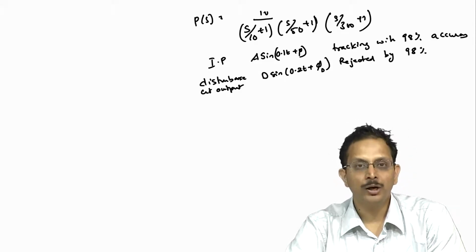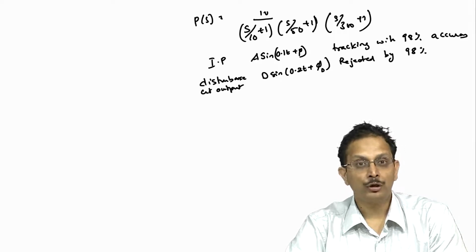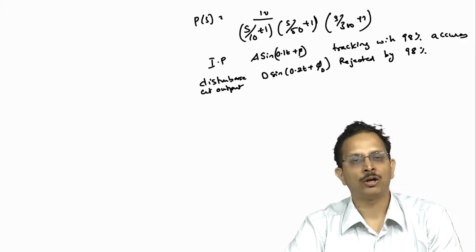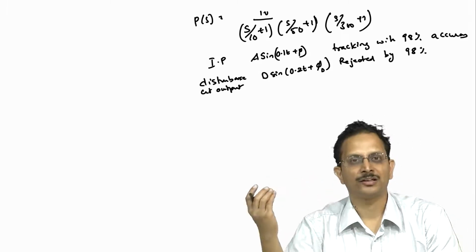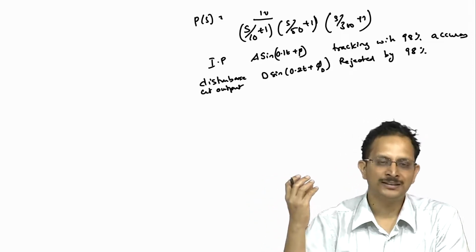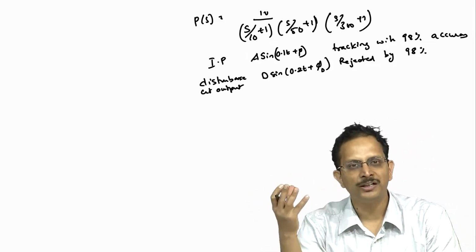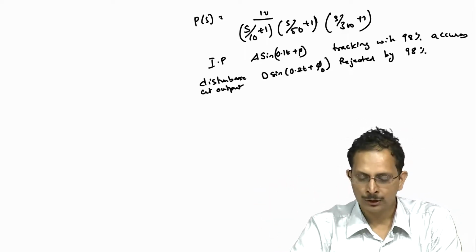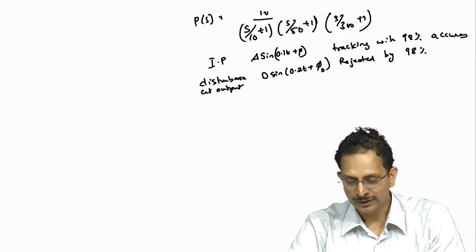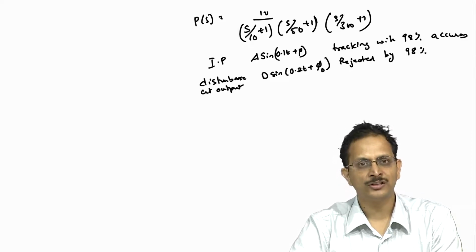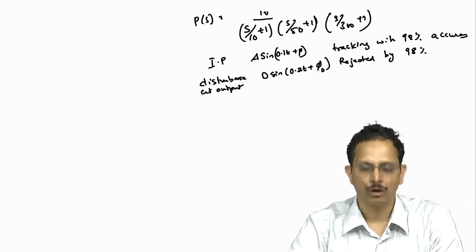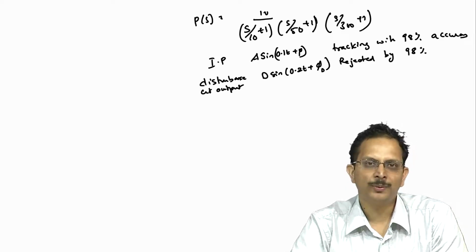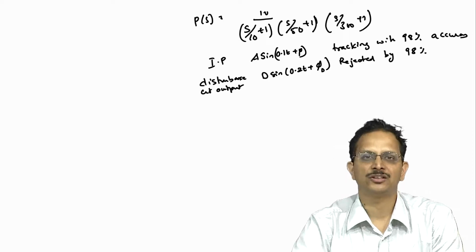Indeed, if one were to look at this problem, it is not even told to you that you are supposed to employ feedback control, or in other words supposed to use a sensor to measure the output of your plant and then compare it with the reference and then manipulate this error by means of some function in order to get the reference to be tracked. So, the first thing that we need to do is see whether feedback control is necessary at all for this case or not. What we do notice when we look at the plant structure is that we have not been specified any uncertainty in the plant's dynamics.